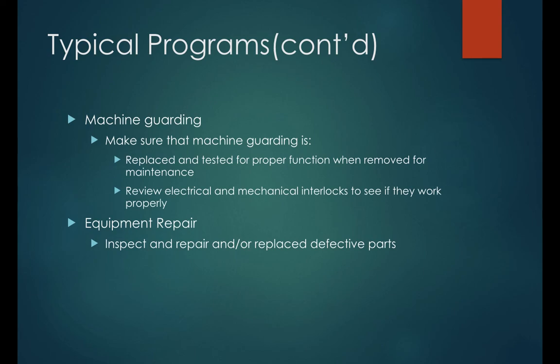Machine guarding is going to be a part of this program. Make sure that machine guarding is placed and tested for proper function when removed for maintenance, and review electrical and mechanical interlocks to see if they work properly.